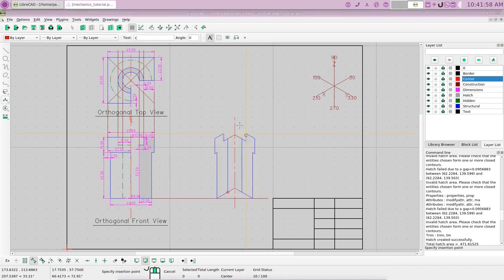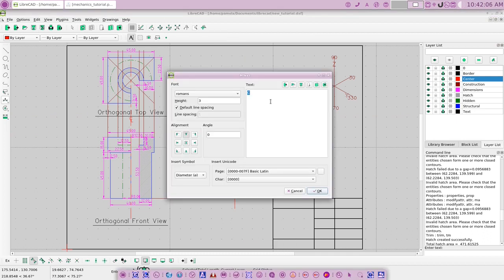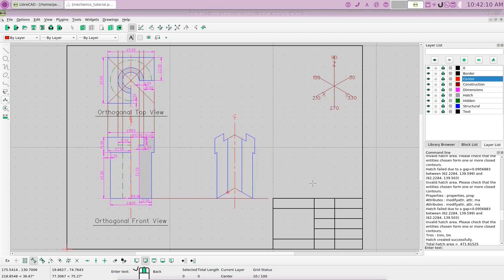Say okay to that, and let's put our C designation there. Okay, now let's bring up M text again, and let's make a capital L, and let's say okay to that, but let's take the end snap off so that we can free snap it, and let's put that L right there. Okay, so there's our center line designation.